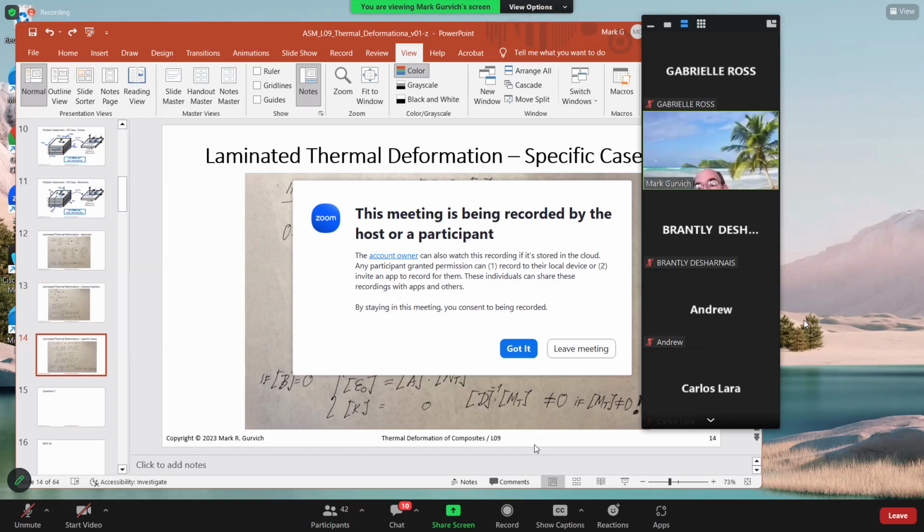So it's a huge issue with respect to quality, and to address it, what is needed is a very clear understanding of how laminated materials deform, even without any applied load. No forces, no moment, but just because of a change in temperature, there will be deformation. And in this situation, it's not that you have it flat at room temperature, then heat it and it starts to deform.